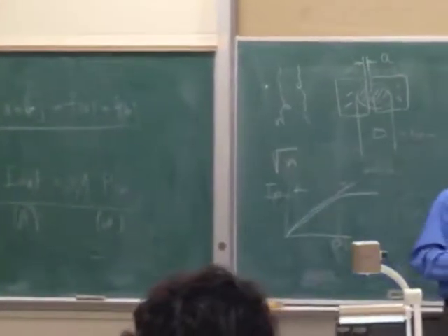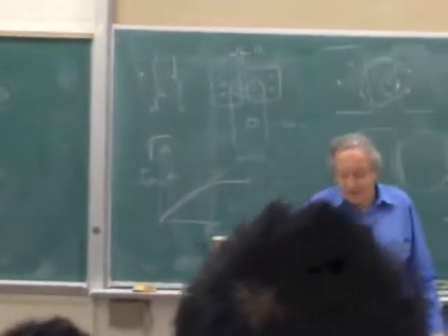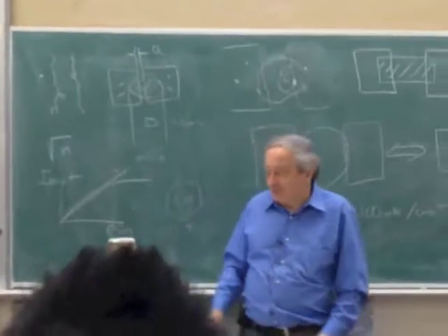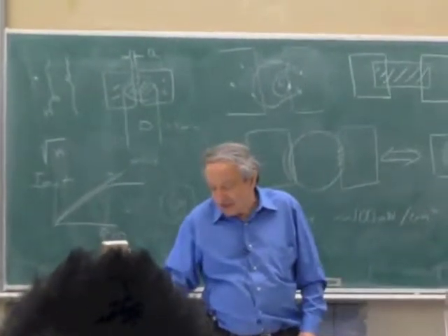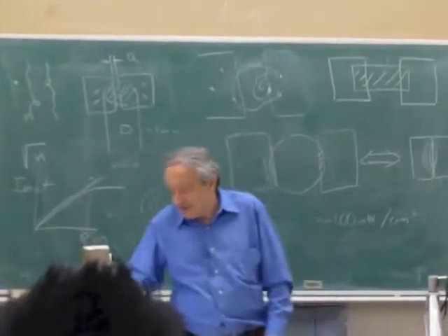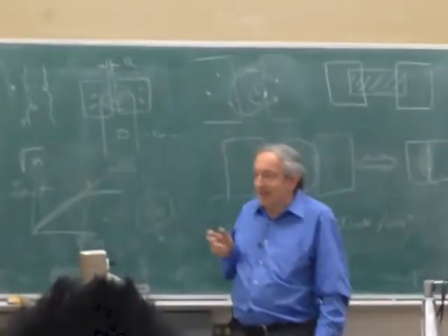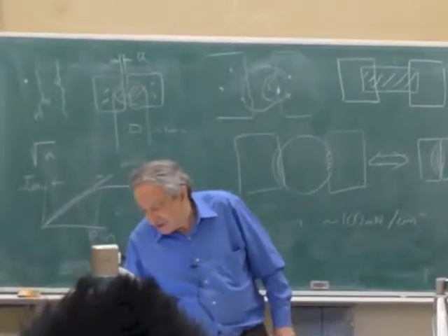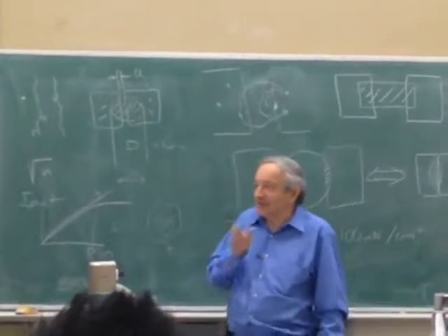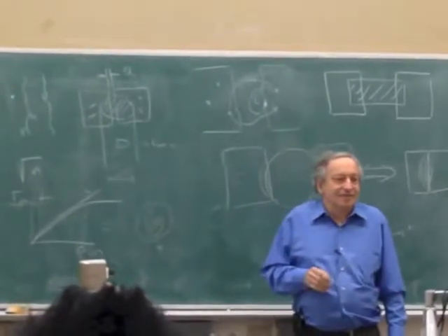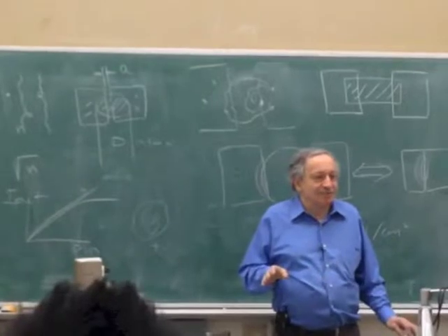So that's why this meter here was moving so violently, because this is a huge power laser pointer. This is actually a 100 milliwatt pointer which saturated the silicon, so I got out of the silicon only 10 milliamp. The meter is a 100 microamp meter, so the slightest movement saturated the meter. Okay? Is that all clear?